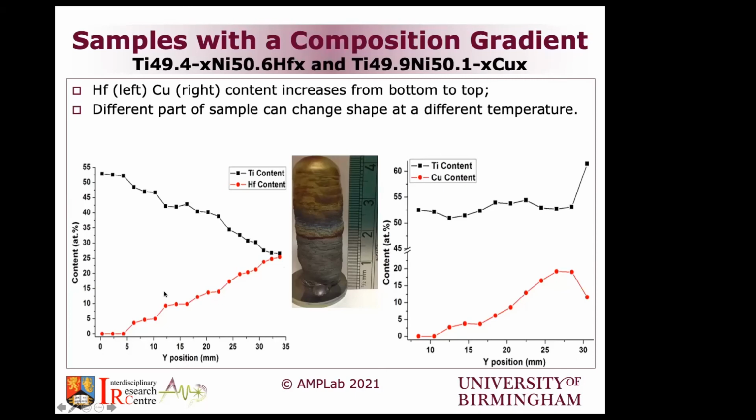In other systems, once you start to change the elements, you straight away get cracks forming. As the material cools down, you see cracks opening up when you have more aggressive intermetallics. The cooling rate, according to our estimate in this process, is around 10,000 degrees per second, which also tells you something about the intermetallics. They are not going to be too big. The cooling rate is fast, as in DLD, and from that point we did not observe defects developing in situ in these two systems specifically. But we saw them in other systems, I admit.